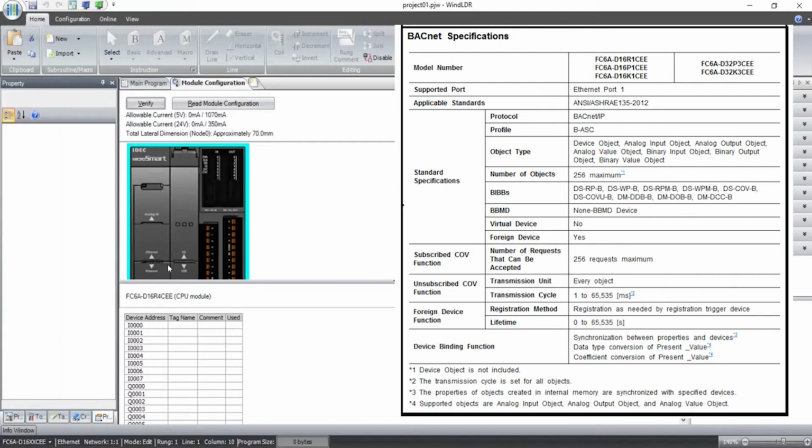It also supports BBMD, which is abbreviated as BACnet IP Broadcast Management Device, which is used to forward and route the data via broadcast communication to other IP subnet networks. At the maximum, we can go up to 256 connections and 250 object creations altogether.